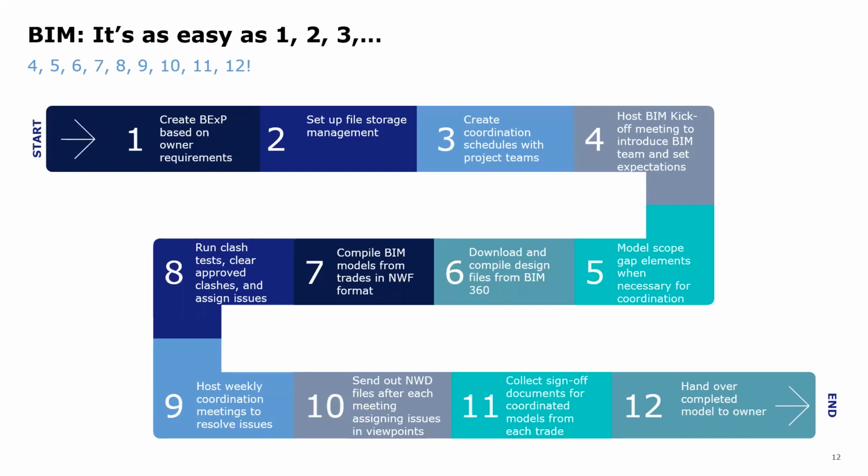If there is a discrepancy, usually it's because in 2D you can't see all the elevations and maybe something wasn't caught in that. But to answer your question, the 2D always rules, and we model for coordination. We just make sure that it can be constructible and everybody has room.